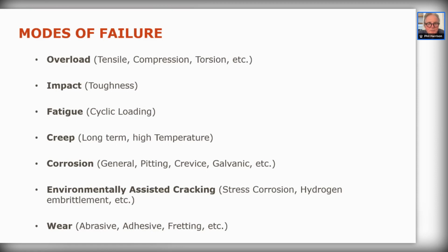And then we have crevice corrosion. Crevice corrosion happens underneath things. You might, for example, have a washer on a nut or a bolt, and that crevice is formed under something. You do not see it happening until probably it's too late. Then we have galvanic corrosion, where things are connected together. And the least noble, as it's called, the most negative material on its own electrode potential, corrodes in preference to the other.